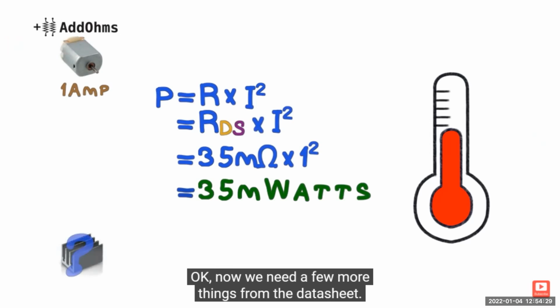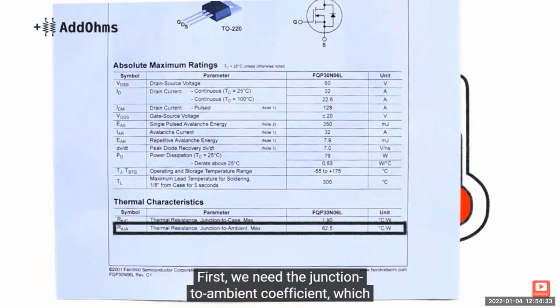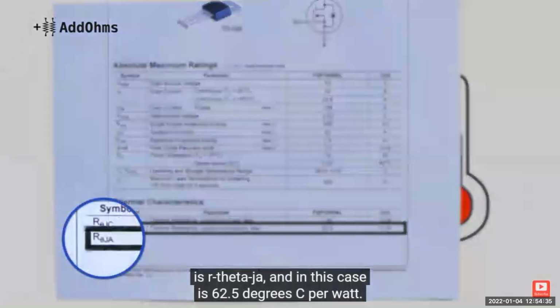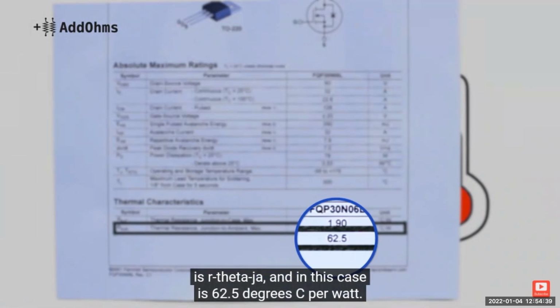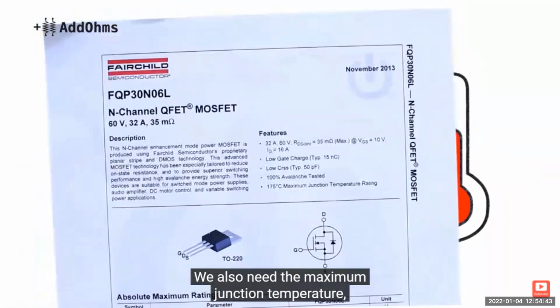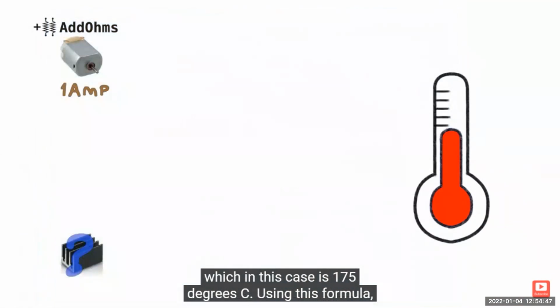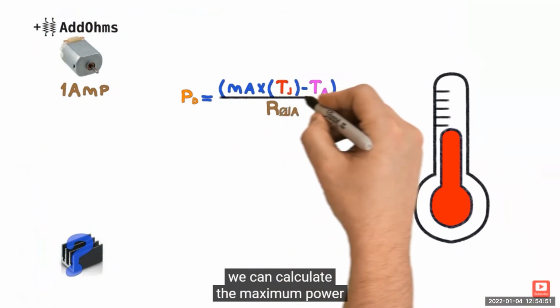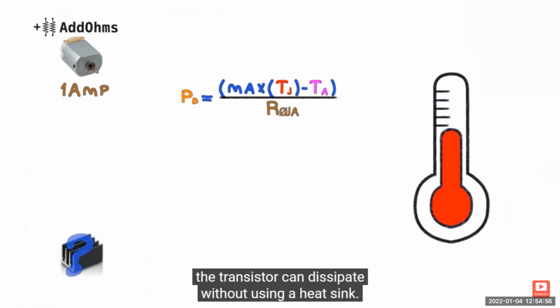Okay, now we need a few more things from the datasheet. First, we need the junction to ambient coefficient, which is R theta JA, and in this case is 62.5 degrees C per watt. We also need the maximum junction temperature, which in this case is 175 degrees C. Using this formula, we can calculate the maximum power the transistor can dissipate without using a heatsink.